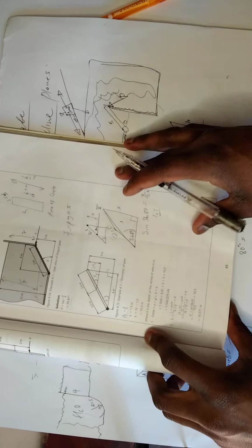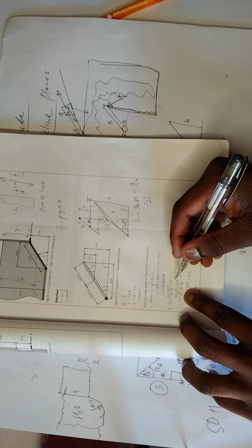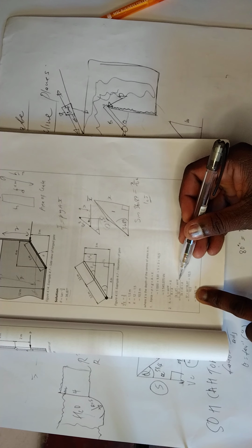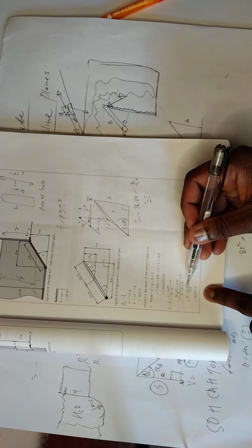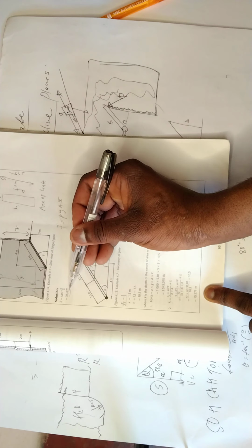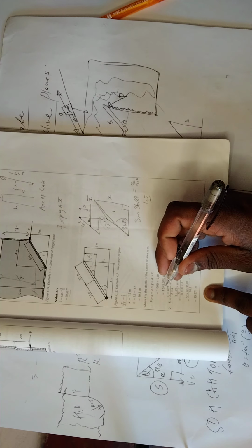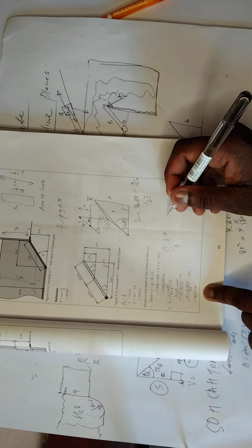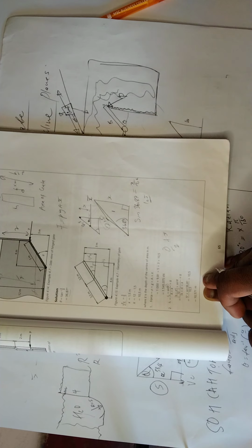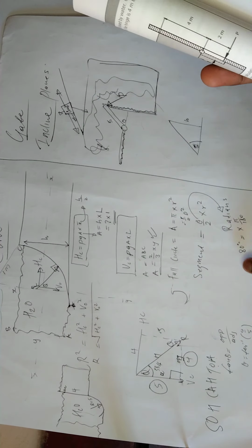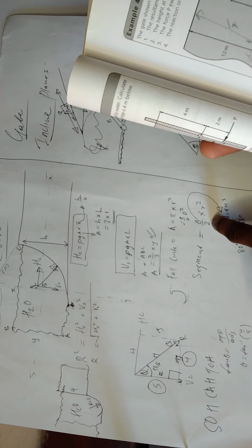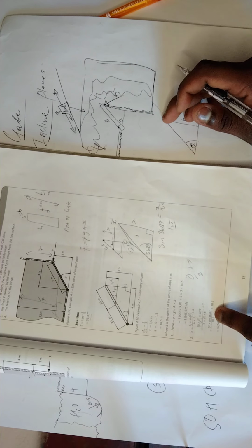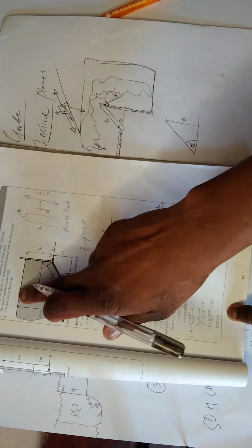So let us continue. It's going to be B and D. Then here it's a sine. On the sine, remember you have already found the angle, which is 36.87. Guys, please don't confuse this angle with the one for the segment on a curve. No, please don't confuse that with this. It's not the same thing, right? So here is the angle you got from the gate, the angle of the gate. Then you put it all together here, then you put in your centroid, then you're going to get your height.